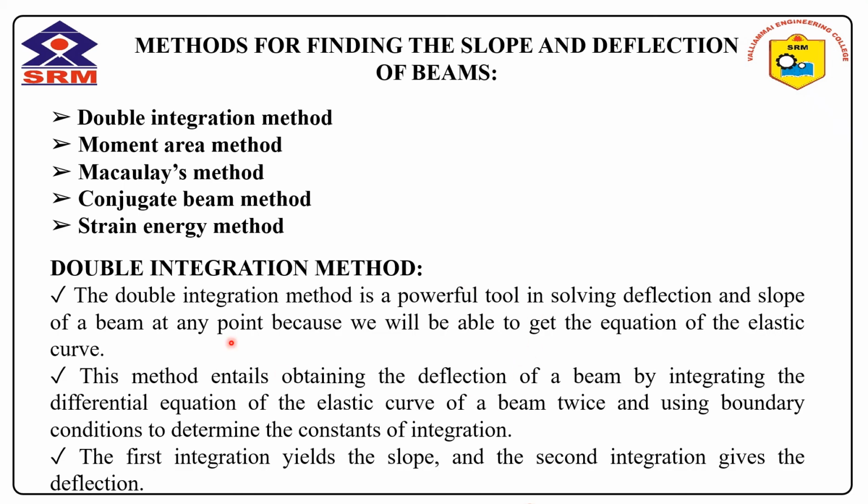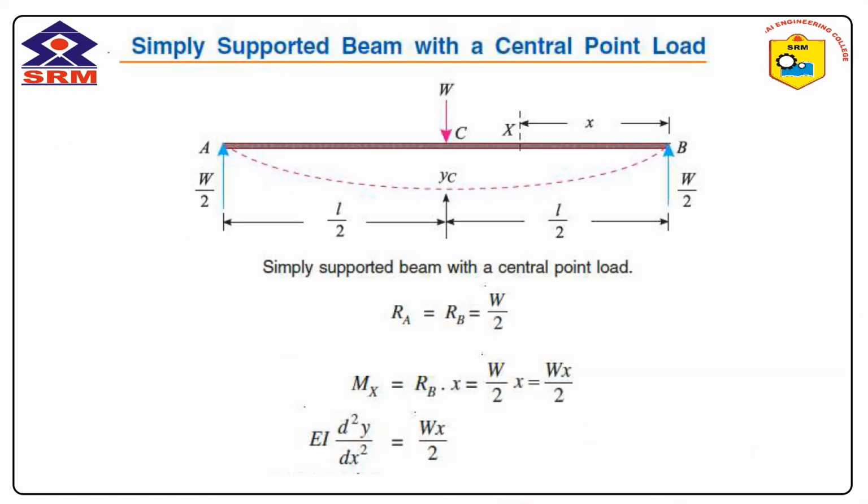From this basic equation, first we need to integrate the differential equation, and we need to apply the boundary conditions to determine the constants of integration. The first integration gives the slope, and the second integration gives the deflection in the double integration method.